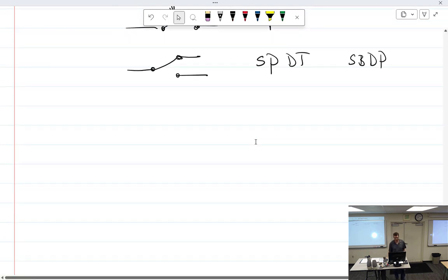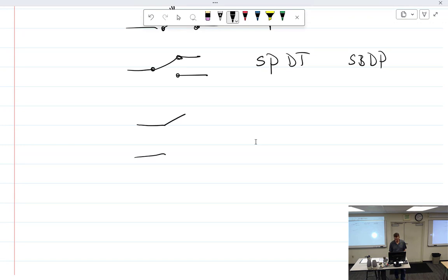All right, and then of course, double pole. And then you have to draw this to indicate that those move together. So how many blades? Double blade, double pole. How many throws, how many paths per each one? It's not a quad, so it's double throw, two paths.